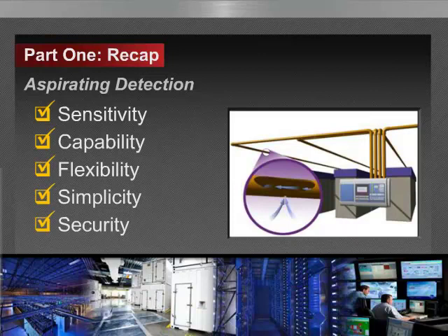They can overcome the effects of dilution by cumulatively sampling aggregation of smoke being actively drawn in by multiple sampling holes. They can monitor all stages of fire development from incipient to fully developed, providing multiple alarm thresholds for staged response. They are virtually unaffected by magnitude and direction of airflow or by temperature extremes. Where a gaseous or sprinkler fire suppression system forms part of the overall fire protection solution, FM-approved aspirating smoke detection systems can be designed to actuate release mechanisms.